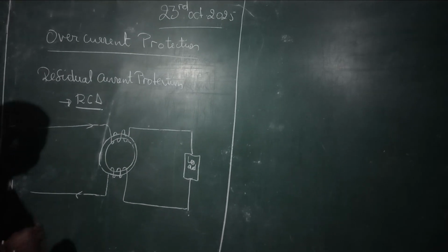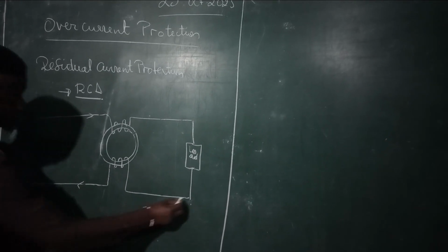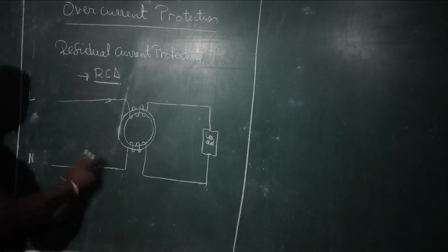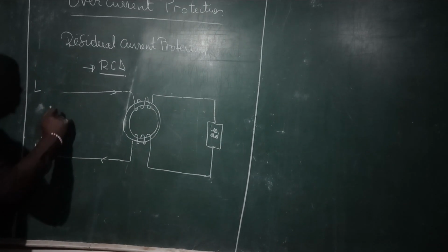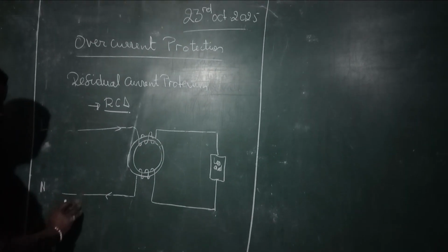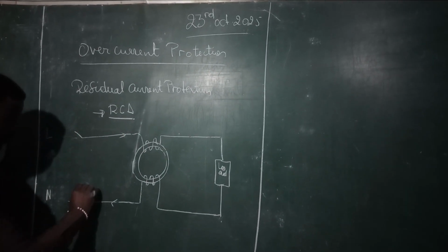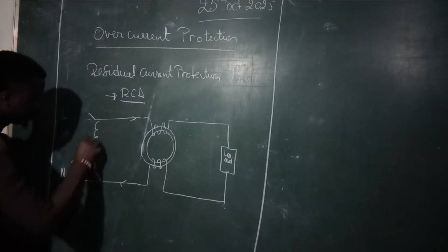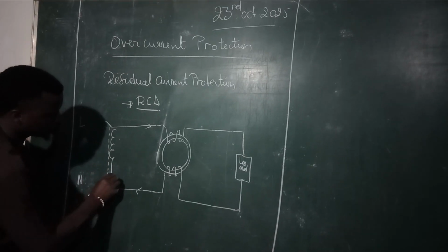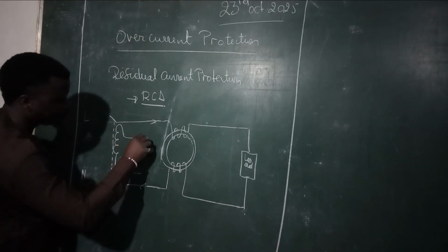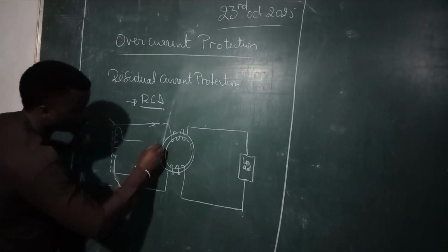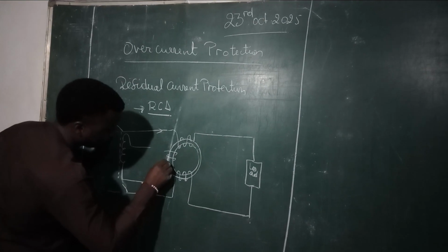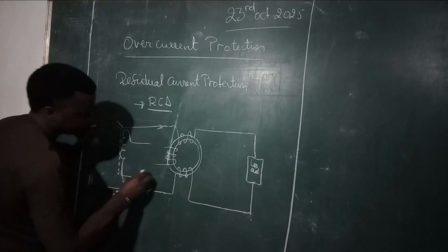But sometimes when the circuit has a problem and the current is imbalanced, we have a tripping mechanism, as in a breaker. This tripping mechanism is a coil which operates by a difference of the flux that comes from the third coil.